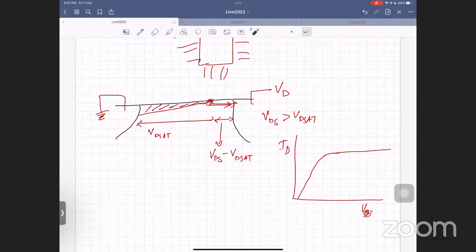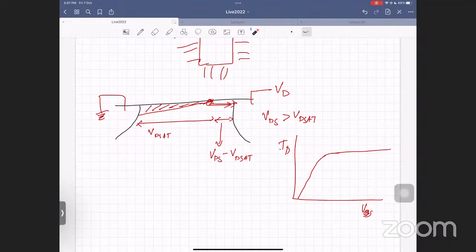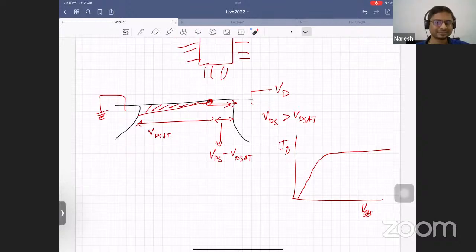Lakshmikant, you had another question? Yes, sir. This is also just a fundamental question. So during scaling, in a long channel MOSFET, the depletion region under the source and drain, we just neglect it. But when we scale more and more, the depletion regions between the source and drain become prominent, and we take them into account. So how does it affect the threshold voltage and the CV characteristics?